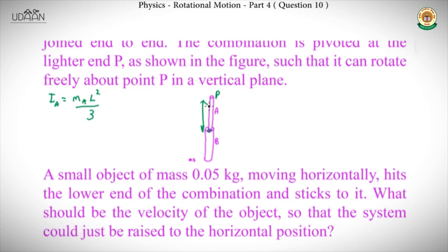However, there's a catch over here. You have made a mistake. You always need to remember that for the parallel axis theorem, the initial axis which you use has to pass through its center of mass. Oh, okay. So you'll have to take an axis passing through the center of mass and then move it to point P. Okay. Right?